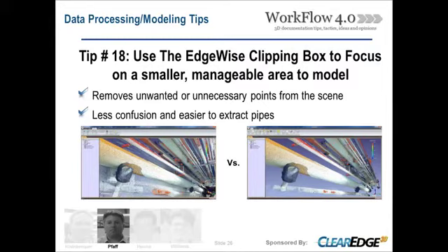If you in Revit utilize the work sets, that allows you to take out and put back in or replace entire model sections without having to go through and pick individual items out for deletion. Gives you a lot more control and also allows you to kind of unify your team as far as being able to have multiple work sets going as far as the MEP modeling goes.